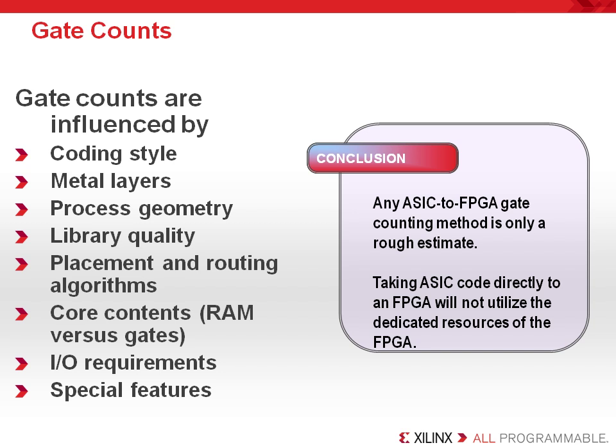But the biggest takeaway we're going to make is that resynthesizing ASIC code directly into an FPGA will not use the device resources to full advantage. You'll have to instantiate resources that are not inferred, and you'll have to make sure your coding style is optimum.